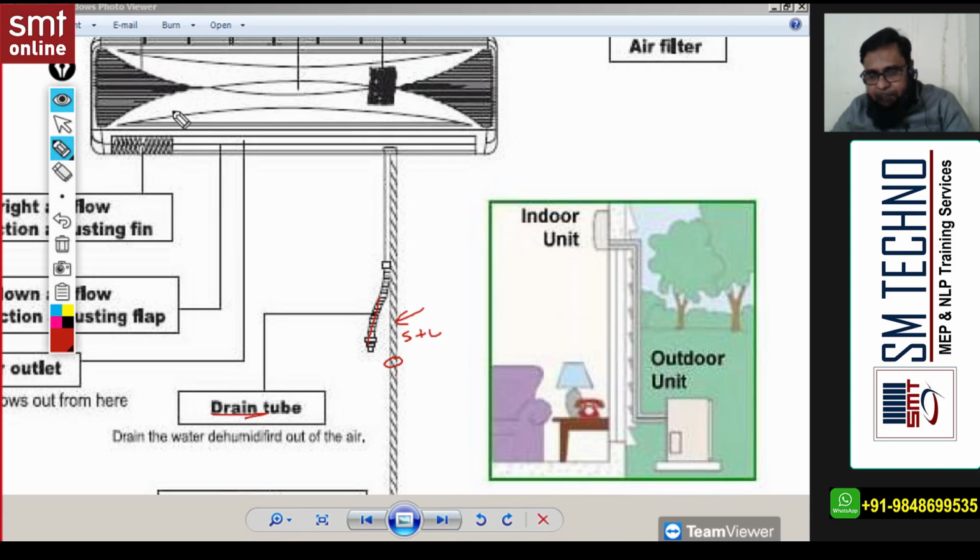Because when the machine is running, on the evaporator coil there is condensation of what? Room air moisture. So at the bottom the water will collect, and this water must be rejected, or else after some time the level increases and it will leak from the indoor unit, or it may be sucked by the air and thrown out like an air cooler, or the wall will be damaged.